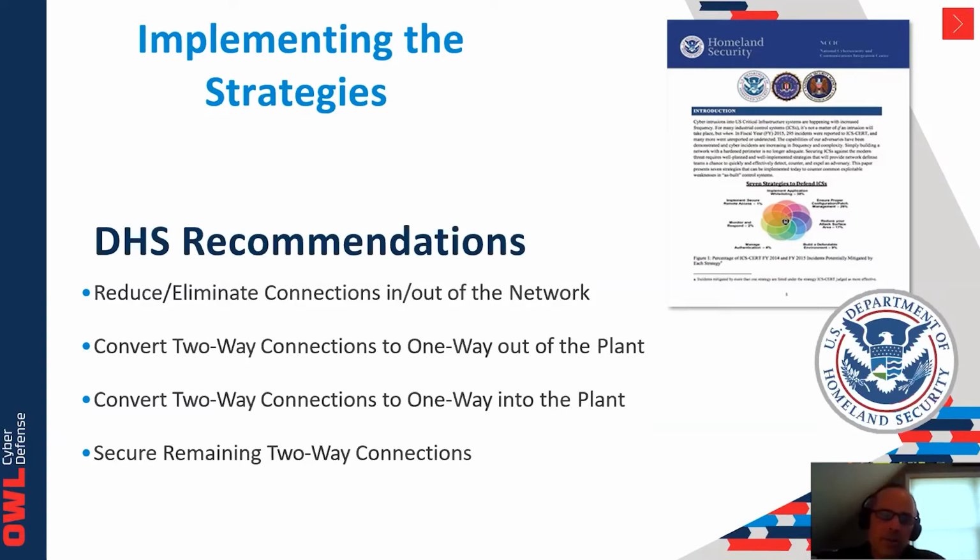They also go on to say that if you are moving stuff into the plant, let's say a software patch or an update, how do I do that in a secure way? And again, the recommendations make that a 1-way transfer into the plant. We need to apply potentially virus checking on that. You can do checksums against that to make sure the patch that you're sending matches the original manufacturer's patch. And there's multiple guards that you can put in place to make sure the information moving into that plant is secure. Do it through a 1-way. That way you know there can actually be no leakage out through the plant through that 1-way in.